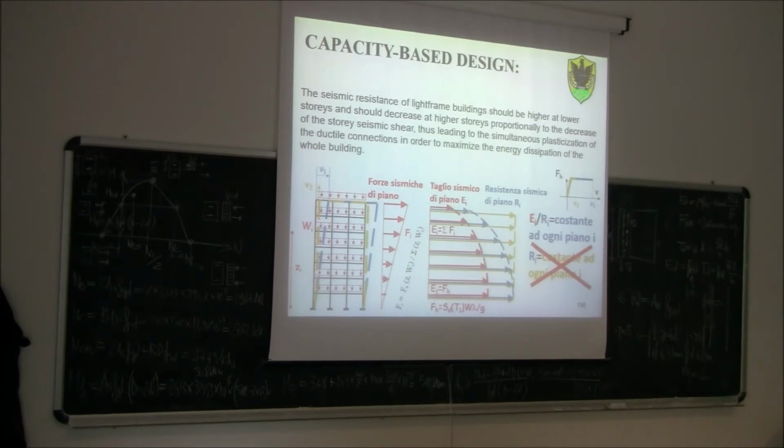Otherwise I have a localization of the energy dissipation in one story, what we call a weak floor mechanism. Instead I want to have a distributed plasticization.